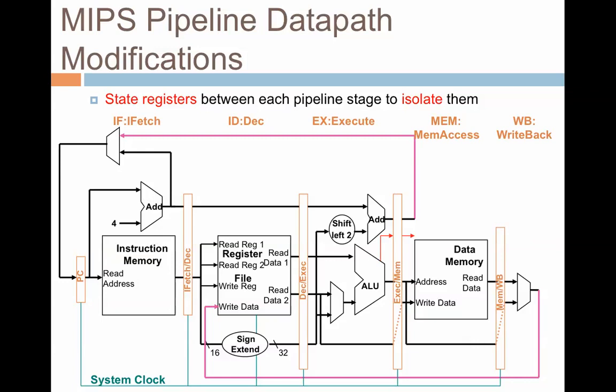So if you want to do a write back, the address of the register also has to move along with the instruction, so that in the write back stage we can write to the appropriate register file. So there will be a signal here where the value moves accordingly, so that at the end of it we will have the right register to write the value.